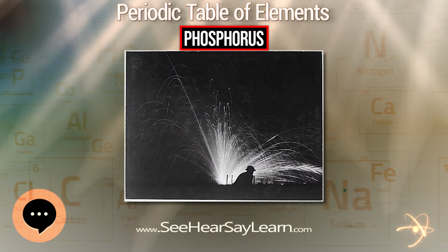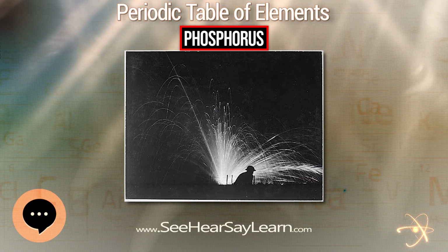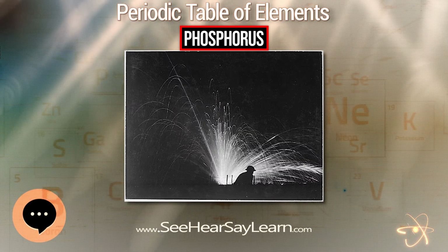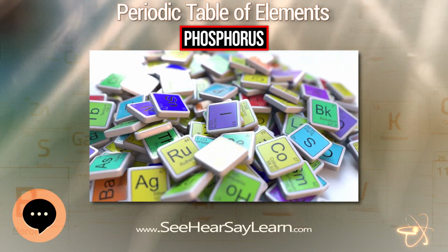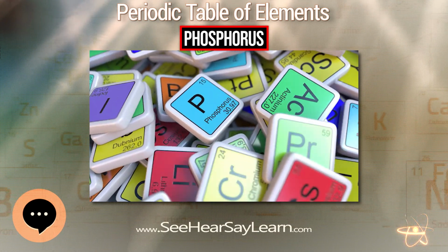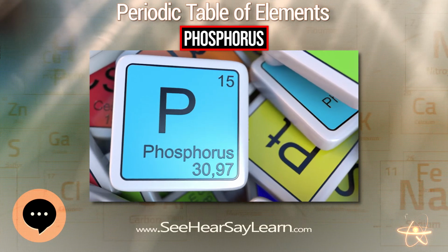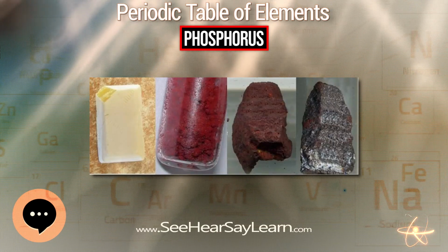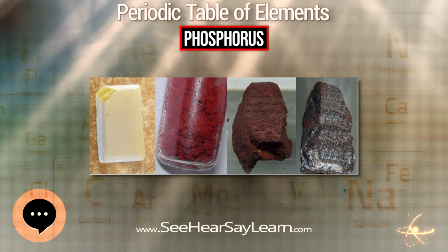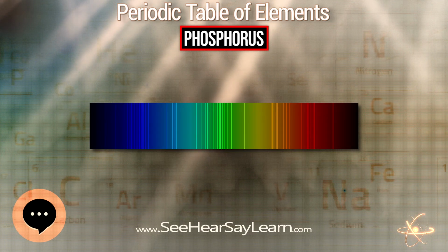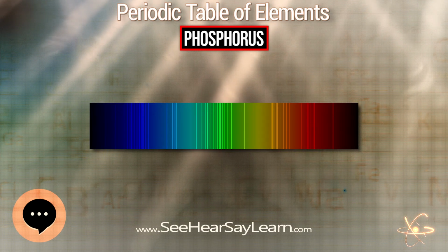Phosphorus is also an important component in steel production, in the making of phosphor bronze, and in many other related products. Phosphorus is added to metallic copper during its smelting process to react with oxygen present as an impurity in copper and to produce phosphorus-containing copper alloys with a higher hydrogen embrittlement resistance than normal copper.